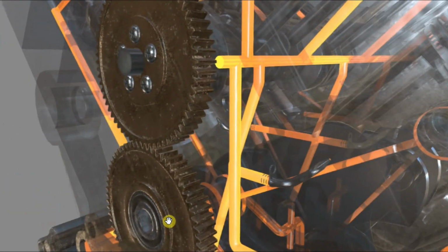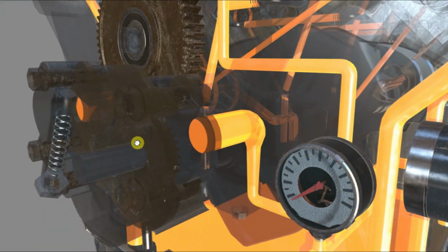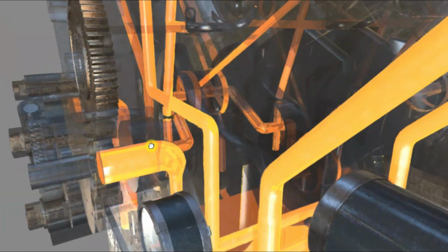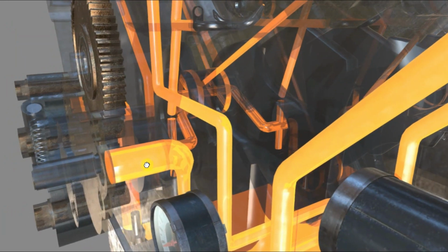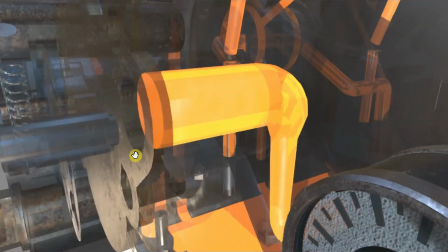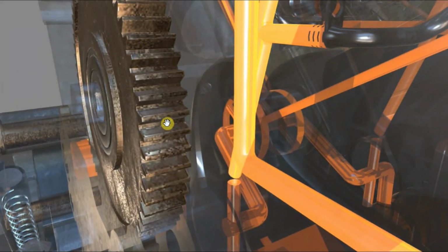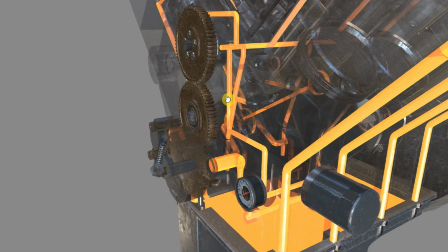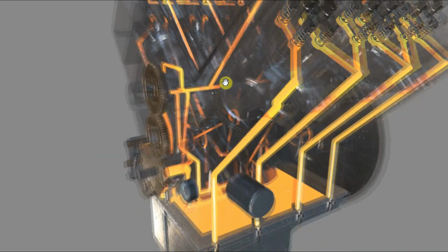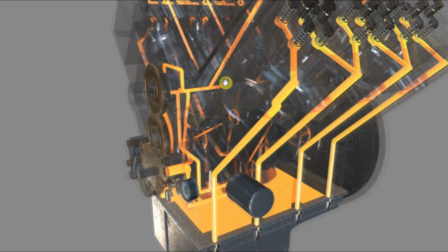We can actually see on this engine that we have some gearing here associated with the camshaft. Looks like it's geared and hooked up also to the crankshaft and the oil pump. The oil pump is driven from the crankshaft itself as well. But what we're mostly interested in for this lesson, rather than go through and analyse the entire lubrication oil system, is the fact that the oil itself is responsible for cooling and lubrication.